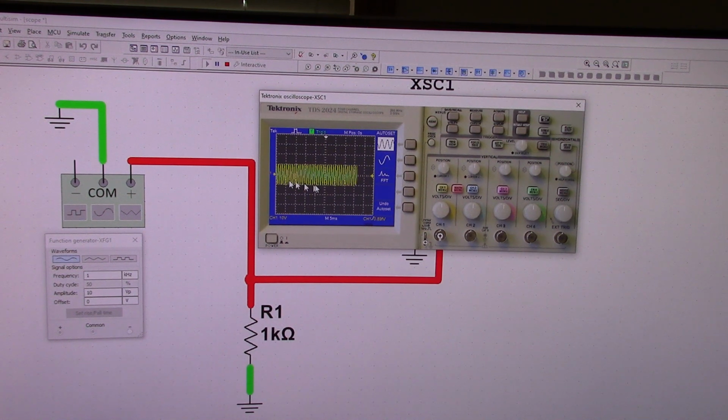Now, obviously, this is not a whole lot better. So what I have to do is spread this out a little bit, and I do that with this button right here, the volts per division button. Well, maybe not. Take that back. You change it with time, which is this one here. Volts per division will do it in the vertical axis, the y-axis. Actually, what I want to do is to change the x-axis, right? So that's this knob right here. So I'll turn that a little bit.